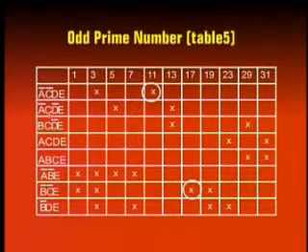In the second step of Quine-McCluskey's method, the essential and minimal prime implicants are found. The prime implicants found in the first step are listed in the leftmost column of the table. The table is referred to as table 5. All the original minterms are listed in the top row. So the minterms are 1, 3, 5, 7, 11, 13, 17, 19, 23, 29 and 31.